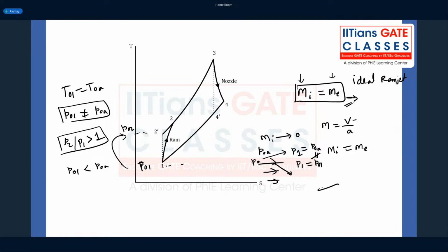so that when the flow comes to a combustion chamber, like say this is my ideal schematic of a ramjet. So when the flow comes to a combustion chamber, you have decreased your velocity from some supersonic speed to very low subsonic speeds, nearly zero. Okay, so in the process, your pressure over here, Pa, is now increased to P1. It is nearly equal to P naught A, not exactly but nearly.